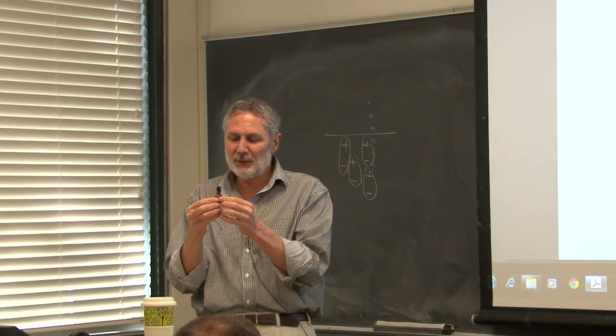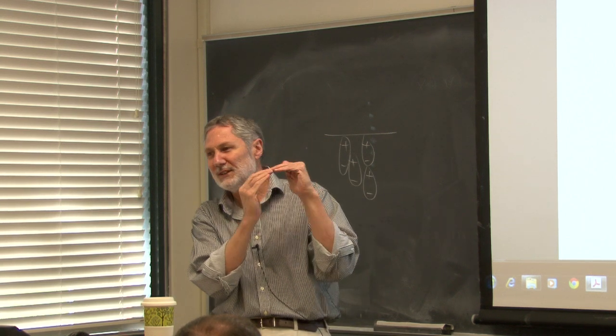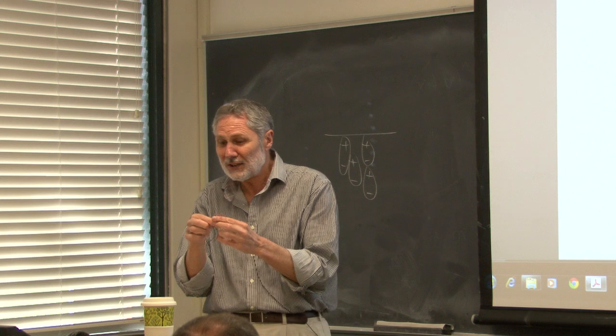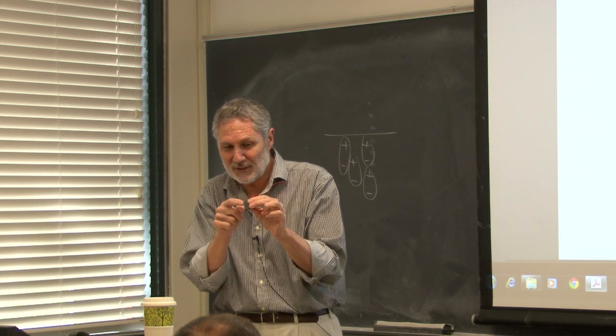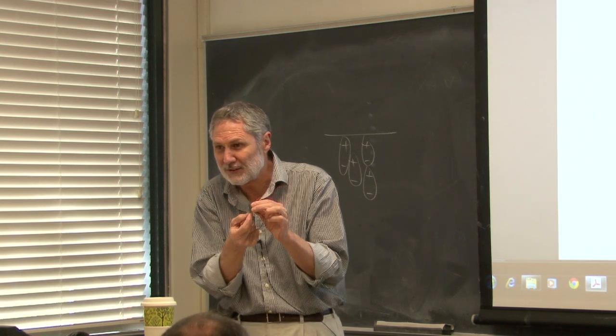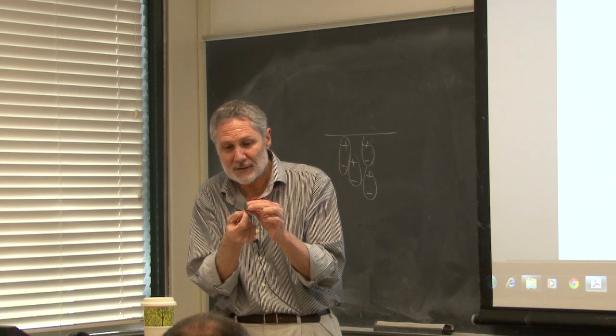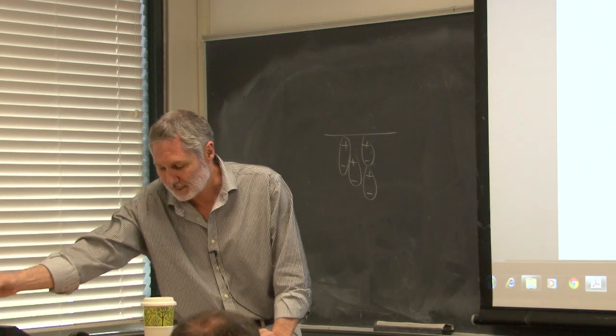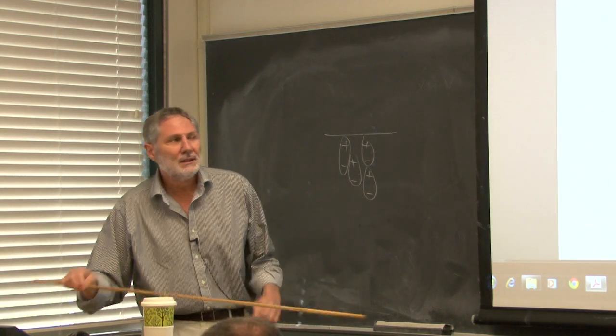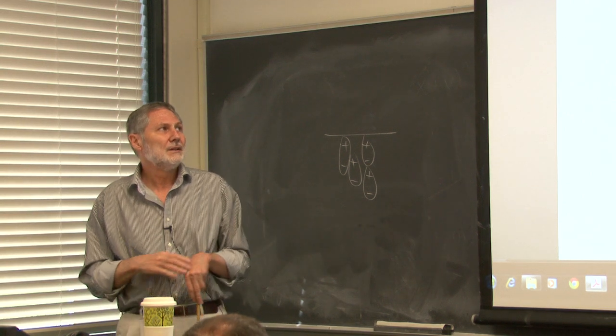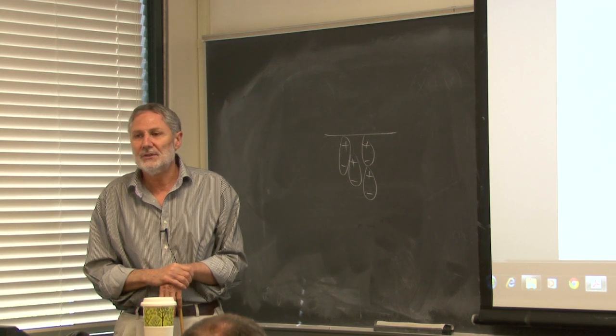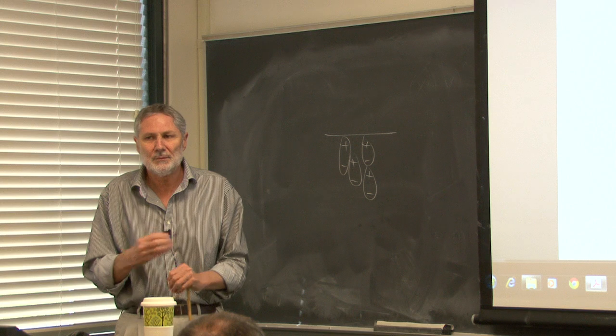And there's one place where you can see it doesn't quite line up. That's a dead giveaway that this is not genuinely segmented. They've just put this outer conductor on the outer surface here. All right? So let me just pass that around. And it's probably done because it's a lot easier to do that than segment a hydrophone. And hydrophones tend to be small.